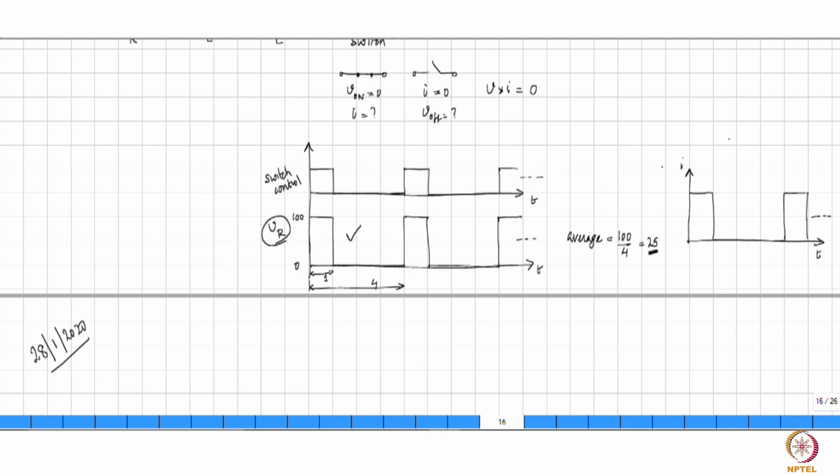While the waveform of voltage is alright, we don't really desire that it needs to be smooth for this application. For certain other applications, perhaps you may want a really smooth DC waveform. That's okay. But in this particular case, this is not so important, but this is important and not acceptable. Now the question therefore is, how do you get a smoother waveform for I?